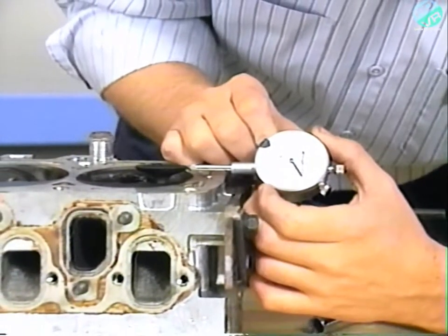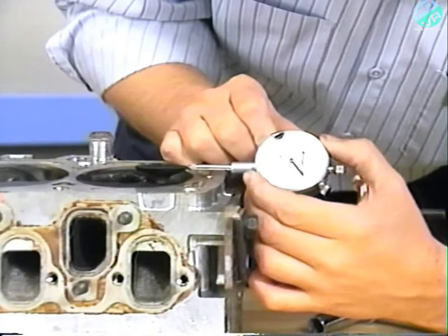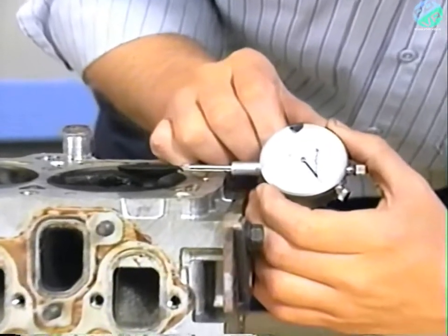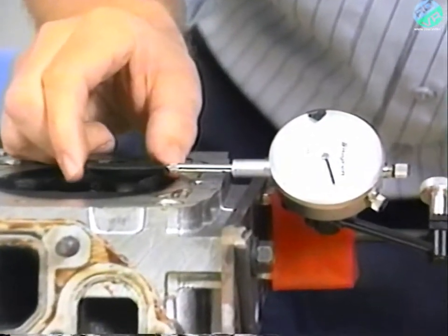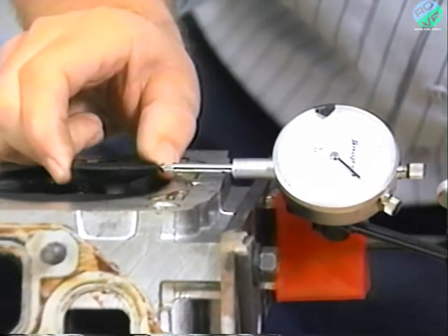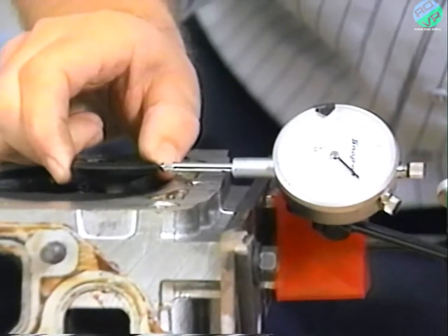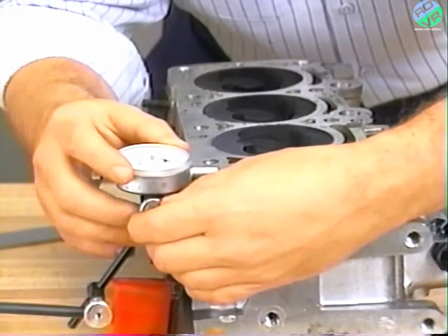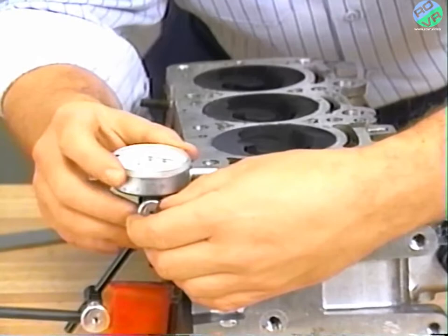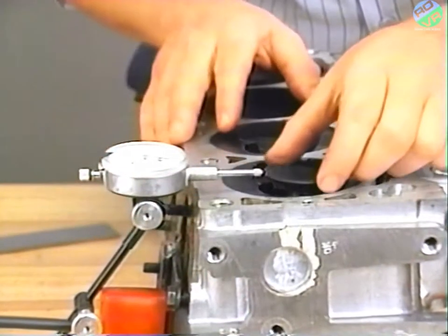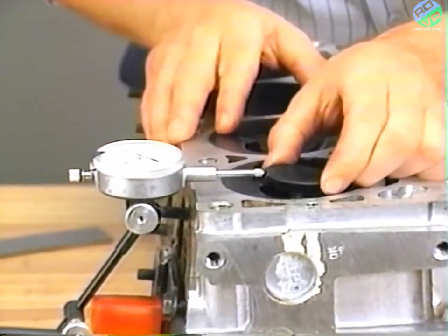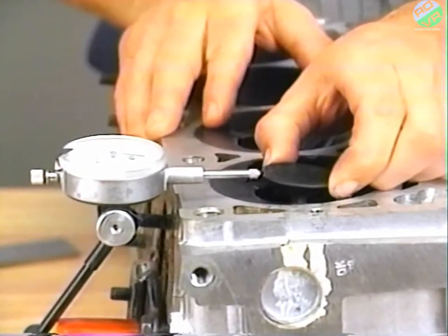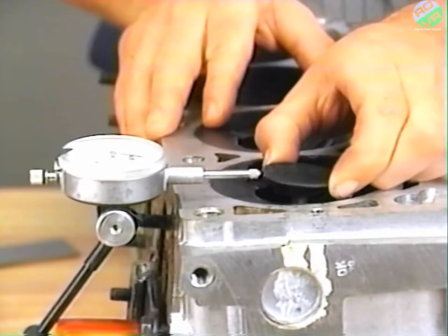Valve guide wear can be measured using a dial indicator. Position the valve head about 4/100 of an inch above the cylinder head gasket surface. Now try moving the valve towards and away from the dial indicator. Readings should be taken both lengthwise and crosswise across the cylinder head. If the dial indicator reading exceeds the specifications listed in the service manual, you will need to ream the guides for valves with oversized stems.